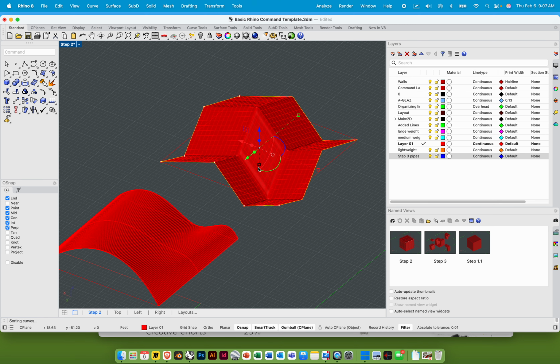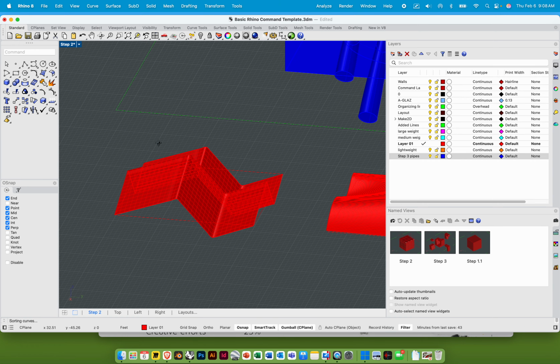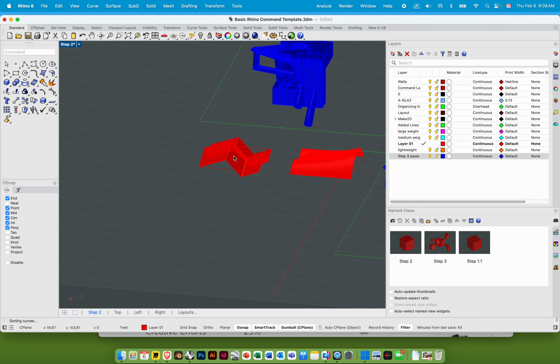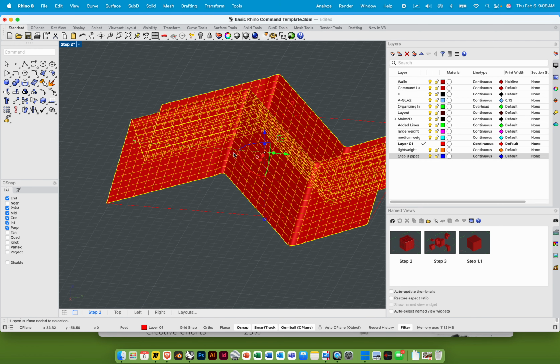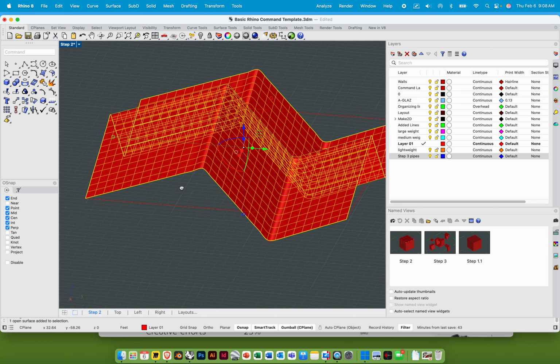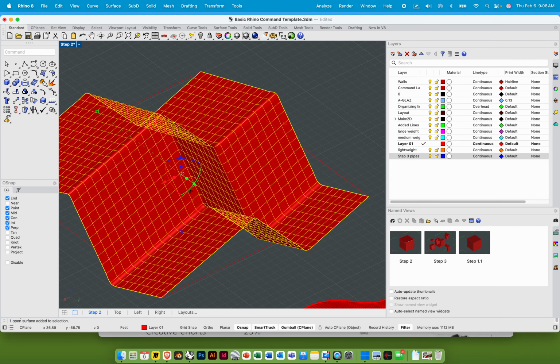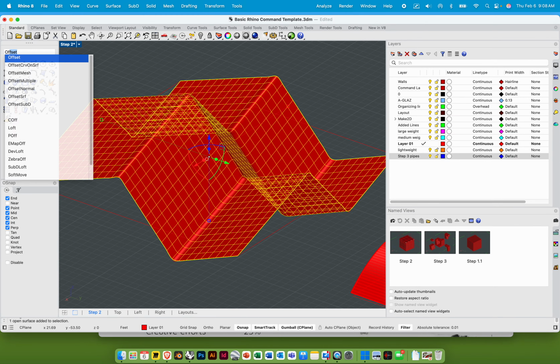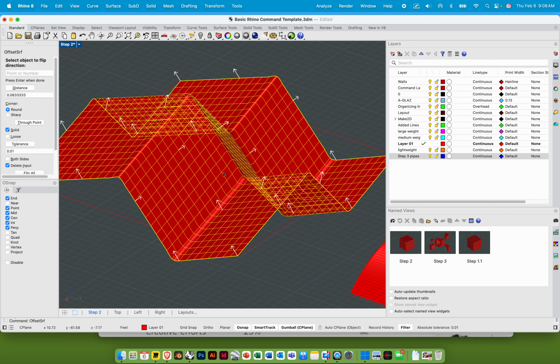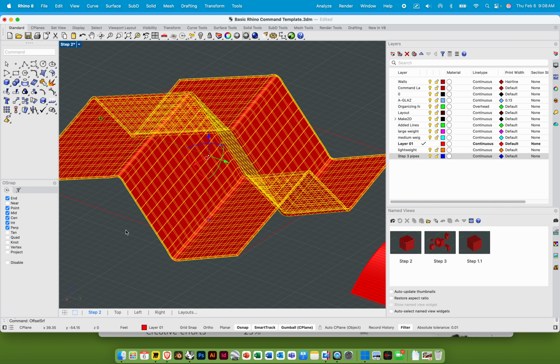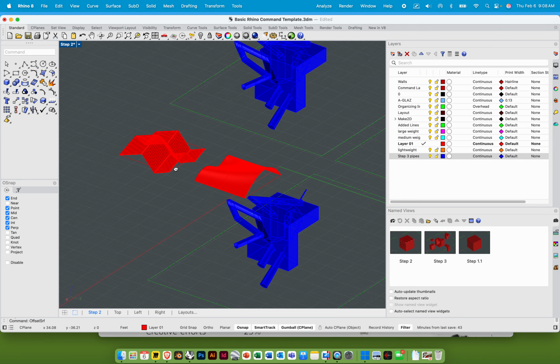I'm going to go ahead and press OK, and I'll probably use this surface today to cut through my last step. I know, all of that just to kind of go over surfaces, but it is important, and I got to tell you, I use surfaces all the time in architecture. So I'm going to go ahead and offset that surface. Enter. And just so that we can see it a little bit better, I'm going to use 3 inches. Enter. You have to hit enter twice for some reason, I guess because there's a little bit more options.